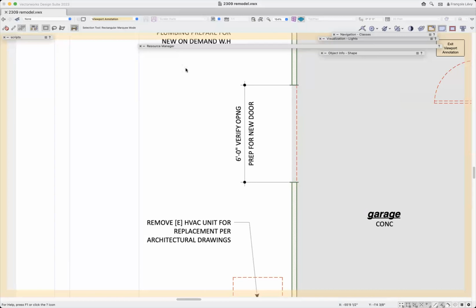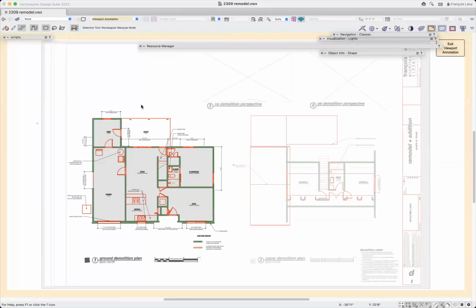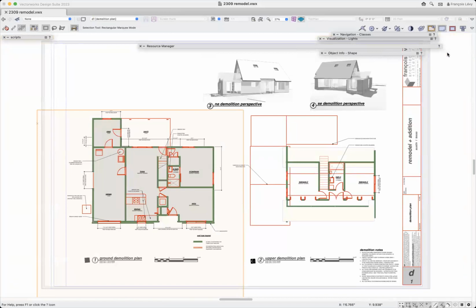Well, I think generally you're just giving them the knowledge of what ultimately needs to be done. What they end up having to do is, like you said about the door, I wouldn't go so far as to account for the new structural framing, because I figured that either in standard details or standard practice they would know what to do. But what they do need to know ultimately is the rough opening. So to me, that was the magic number.